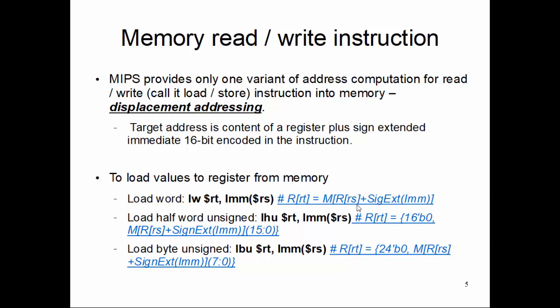This address is calculated from R of RS, the content of the RS register you supply in the load word instruction, plus the immediate 16-bit value, which gets sign extended and added to the RS content. That becomes the memory address you are accessing.